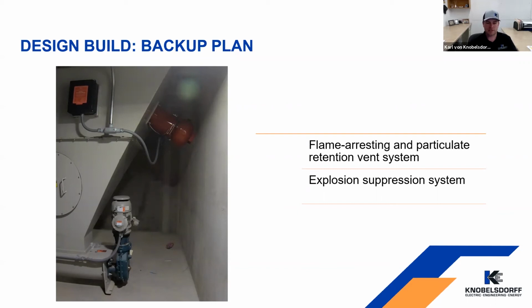So FlameX, BS&B, FIKE, there are lots of different options for these types of systems, but that is a very common thing we see going in now, and we install lots of this on new facilities as well as going back into existing facilities. Part of the DHA identifies some of these issues that may exist, and having installations that don't meet current NFPA guidelines, and then we'll come in and install explosion suppression and venting systems.